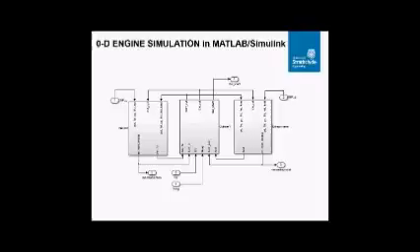Within each zone, the temperature is assumed to be uniform but different from zone to zone. The pressure throughout the cylinder is uniform at any instant. For the calculation of the cylinder working fluid thermodynamic parameters, the mass and energy conservation laws, as well as the ideal gas state equation in the control volume that encloses the cylinder, are used.